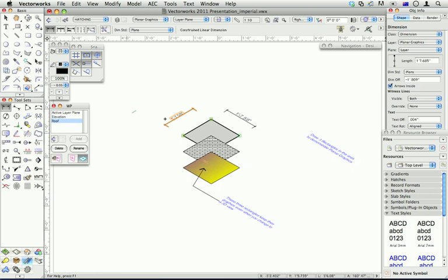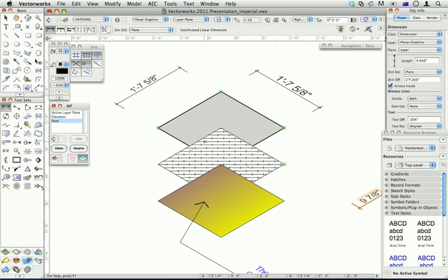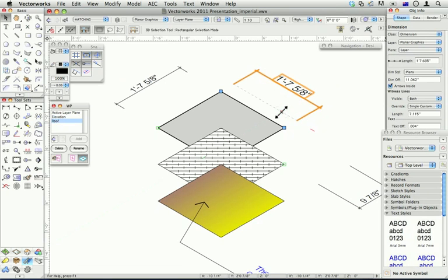You can work in this planar method, so you can have these sort of pseudo 3D dimensions. They do look like real 3D dimensions, and they'll dimension anything on the plane. As long as you use a working plane, then you can put dimensions in 3D. One of the changes with dimensions is this little dashed line which controls the witness line length. So now it's a lot easier to control your dimensions.